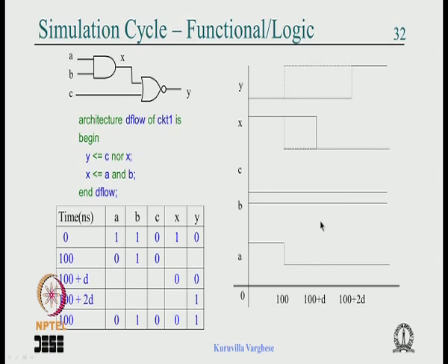Now there is one thing you have to keep in mind: the delta cycle is used by the simulator to keep the proper sequence in computation. So you do not have to worry, you just write the statement. It is the simulator's way of resolving the sequence by adding the delta delay, the delta cycle. It is not too relevant in synthesis. When you write code, I have seen students get caught up in this delta cycle.